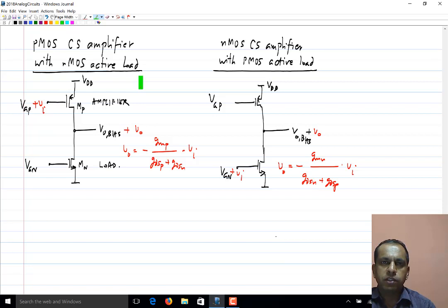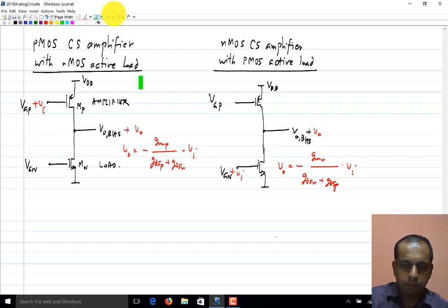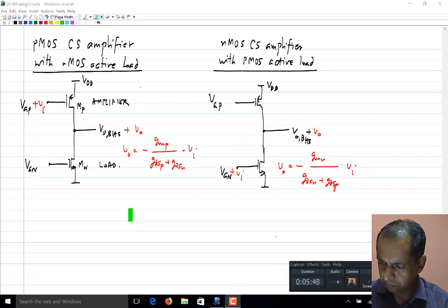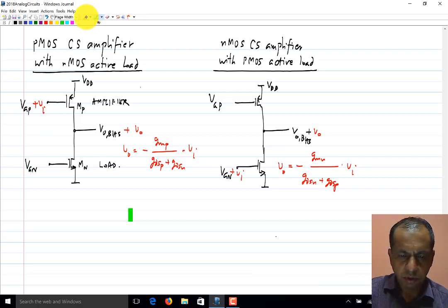We already know that if you have a circuit with a certain polarity of transistors, you can flip them, that is, turn all the NMOS into PMOS and PMOS into NMOS while not changing the behavior of the circuit. We can convert from one type to another. We could have got the second circuit from the first circuit by doing exactly the same. Okay. If you look at the circuits for a little while, a new variant becomes immediately obvious. Here we are applying the input to the PMOS transistor, here we are applying it to the NMOS transistor, and the circuits are the same. Why not apply the input to both? So we could also do this.